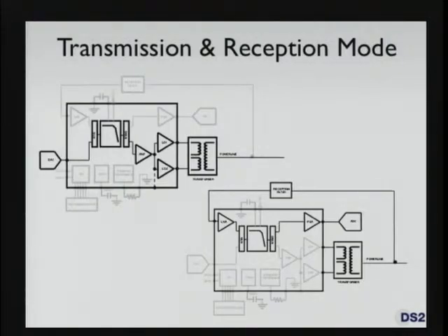This is the analog chip, which basically is a transmitter and receiver in one chip. It has the low-pass filter and the line drivers for putting the signal with the right voltage. And then at the receiver, when it operates in receiver mode, it has an external reception filter, low noise amplifier, low-pass filter, and then it goes to the analog converter.